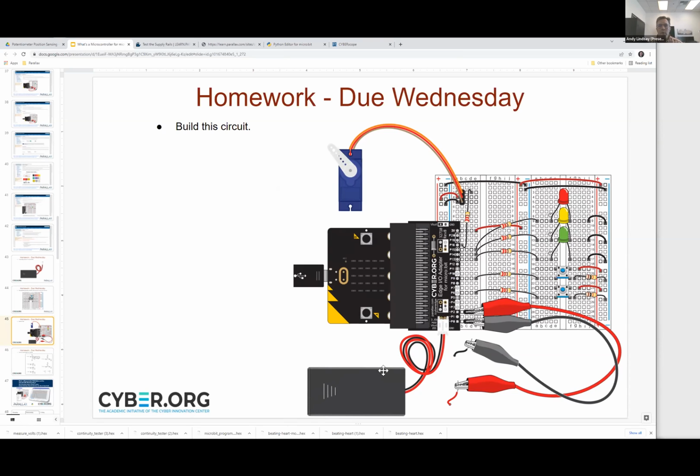Also, with this battery pack, leave the batteries out, because we want to do some testing before we connect battery power. And this servo connection that you see here is on another 3-pin header that's pushed into B3, 4, and 5. I'm going to go ahead and email you a more full write-up on it.